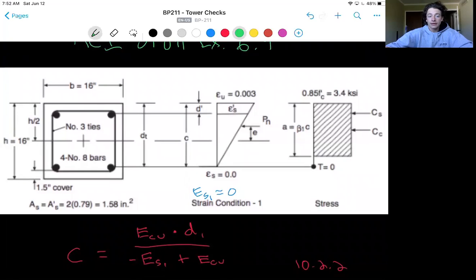Now, after back calculating c and setting ES1 to 0, we can use the same equations from the previous video to calculate all of the terms needed to get axial and flexural capacity. This is why it's important that you've done this all out already and got it all figured out. I have a photo posted in this module so that you can check your work. Your numbers won't be exactly the same, but make sure the signs are correct.